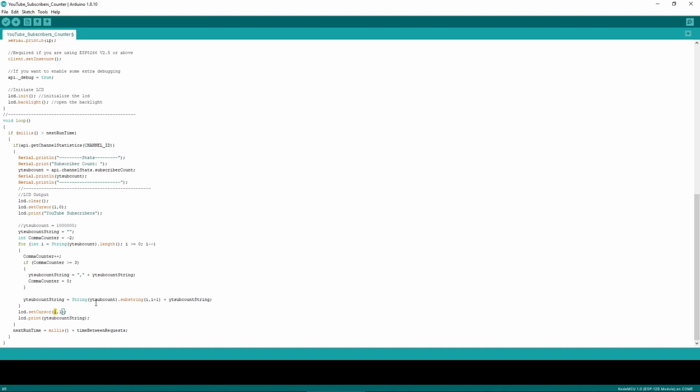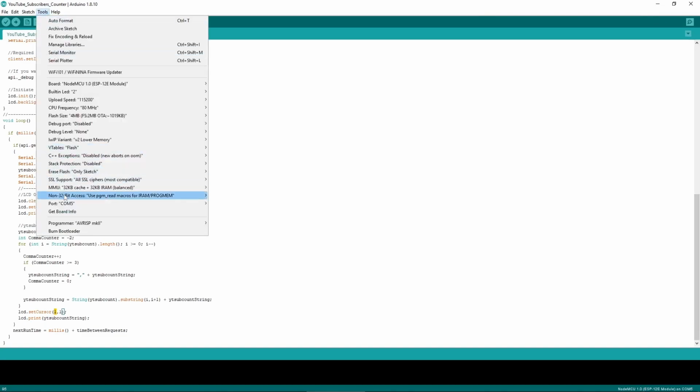So now you're ready to connect your ESP8266. Get your micro USB cable and connect it. Hopefully your CH340 drivers are configured properly. Go to Tools, Port, and make sure you specify the last port that appeared in the list. In my case, it's COM5. It could be COM6 or any other number depending on where you connected it on your computer. So this is configured properly.